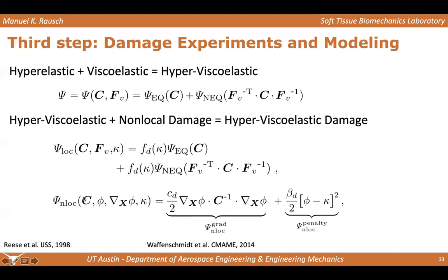So we actually implemented a non-local damage formulation that was published by Waffenschmidt and many others. So this is not the only one, but this is particularly what we use. Essentially, we use a gradient approach on the non-local damage field to regularize the damage across our non-local volume.